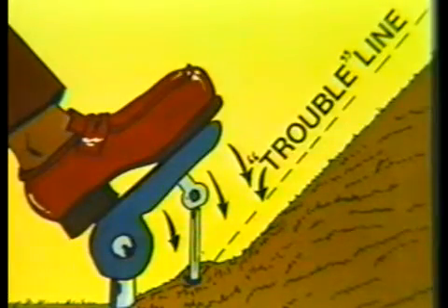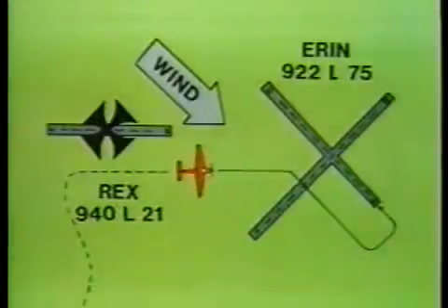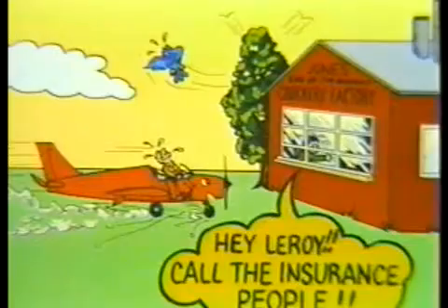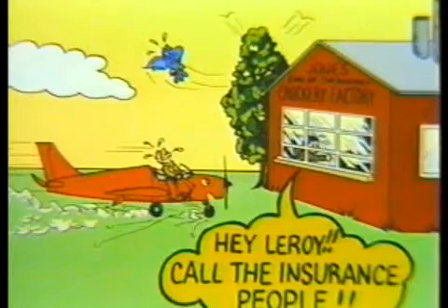If your brakes feel mushy or soft or go to the floorboard, you know you've got a problem. The best action to take in such a situation is to arrange to land on a longer runway and, if necessary, at another airport. Also, make sure that you land as nearly into the wind as possible. It's very poor technique to learn about brake problems when you're on rollout.